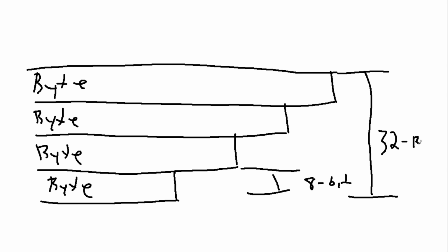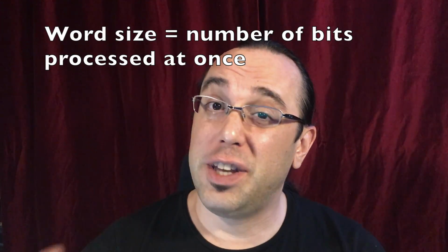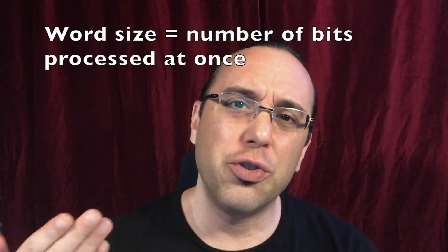And that relates to word size. And when we're talking about words, we're not talking about words like and, if, for, nor, yet, but we're talking about data words. And whatever data word matches your bits, that's your natural word size, i.e. the type of word that's used in the basic processing on that particular processor. So if we're just talking about the word size, we're pushing with 8-bit, 8 bits at a time. So we're pushing this much data. With 32-bit, we're pushing 32 bits at a time, so that much data.